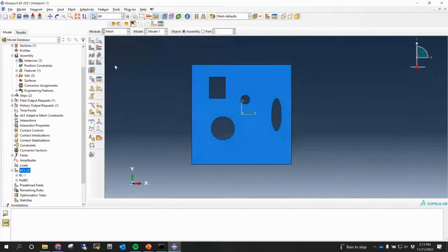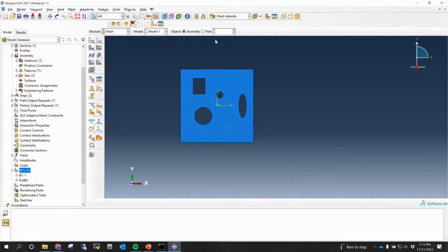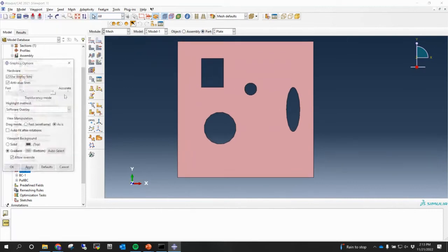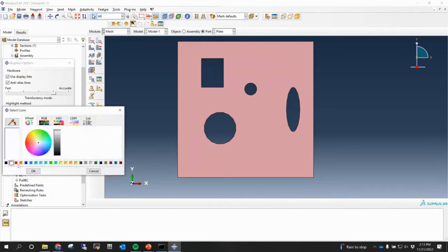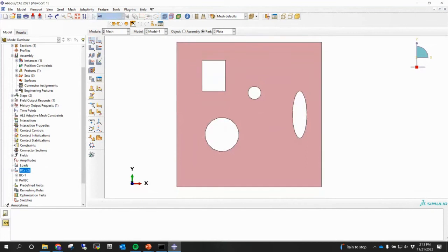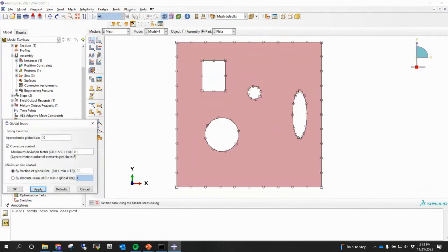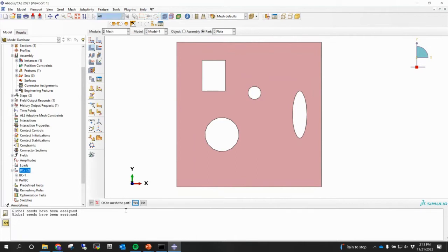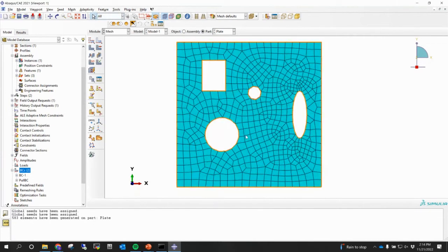Now let's go to the mesh. So for mesh, actually, let me modify something here. I think it's more friendly if we have a white background. So for the particles, sorry, for particle node, for the initial mesh size, let's go with 5, all right? So it's kind of a coarse mesh. And I'm gonna go here and mesh the part, all right? Not our best job in meshing, right? But we're gonna let Abaqus take care of this and suggest a better mesh.